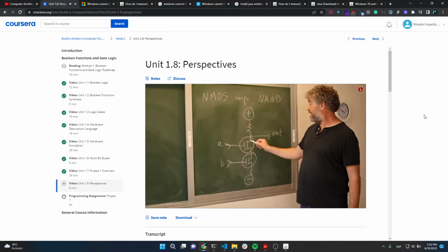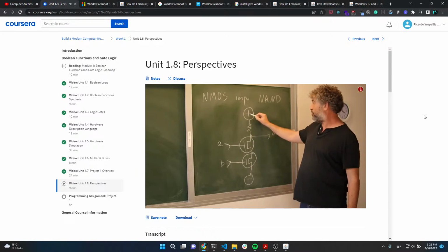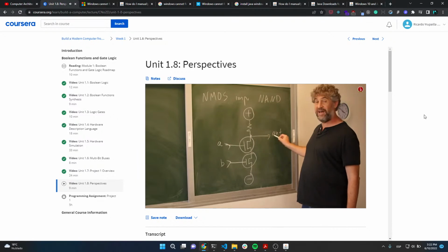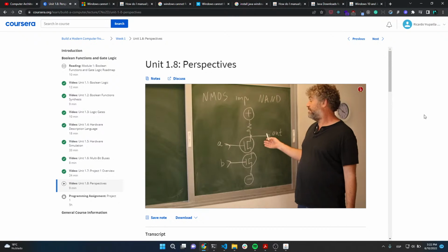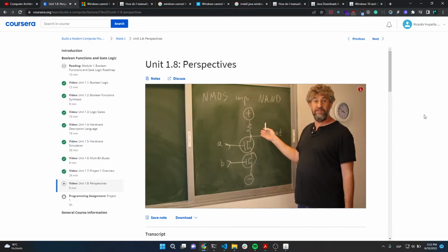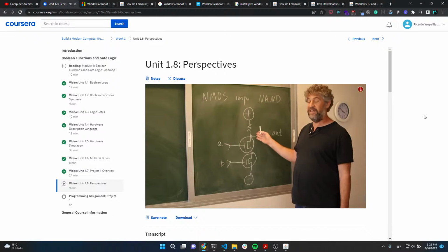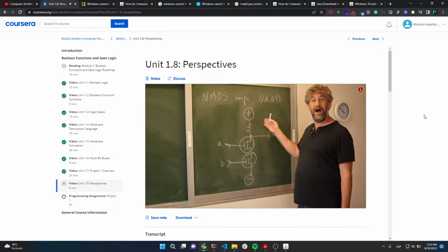In any other case, one of these two inputs is going to be negative, which means a low voltage. The transistor connected to the low voltage input is going to disconnect the two terminals, in which case there is not going to be a connection from the minus sign to the output, and so this weak connection to the plus is the one that's going to rule, and we're going to get a plus output, which is exactly what we want in a NAND gate. So this is an NMOS implementation of a NAND gate. There are many other technologies. This one is not used so much anymore since the 70s or 80s. The important thing in this course is we do not care about the technologies. We want to abstract it away inside of gates that get true and false and output true and false, and we don't care how exactly.